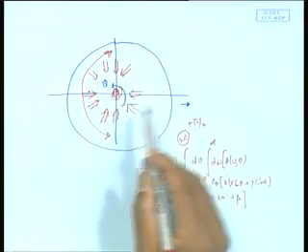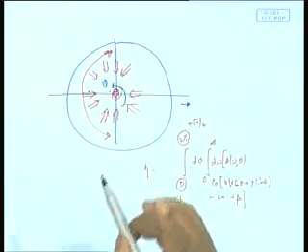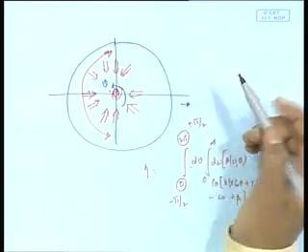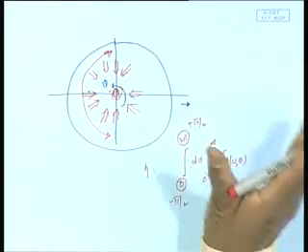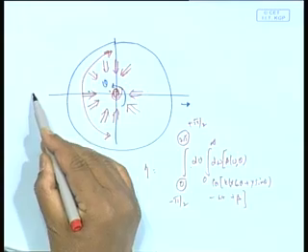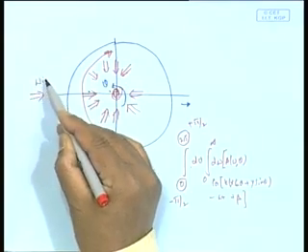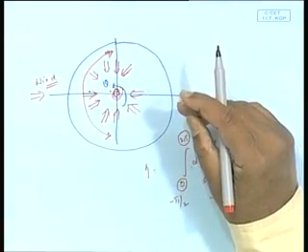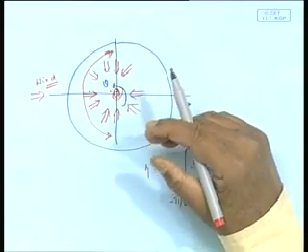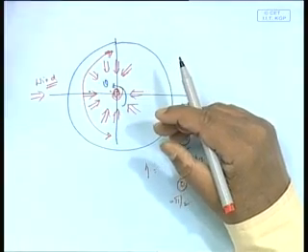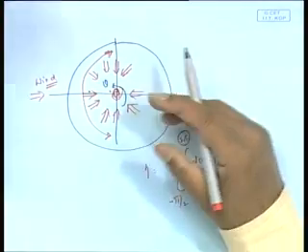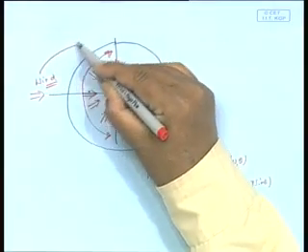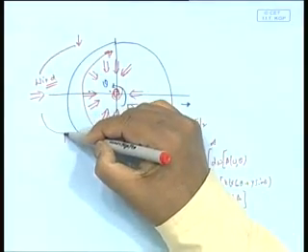Why? Because remember, waves are created because of winds; these are primarily wind driven, wind generated waves. So wind is going to blow in some direction, and you would expect most waves to be in that direction. But we are saying that waves can come from 90 degrees plus or minus, that is 180 degrees. Obviously this will be the primary direction, and waves will also come from somewhere in this direction and up to this direction.